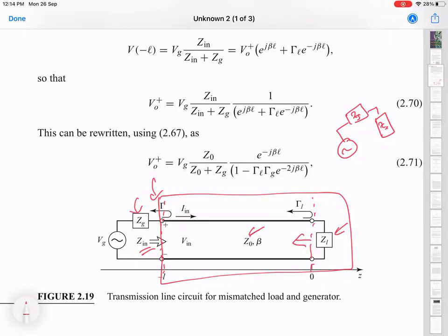This is not true if the impedances are different, because then you have both reflected and transmitted waves. The same thing applies when you look at it from the other side, if ZL and Z0 are the same. When we talk about things being the same, almost for all practical purposes these are all real characteristic impedances and real load impedances. Transmission lines with imaginary characteristic impedances are very, very rare, something we won't worry about.